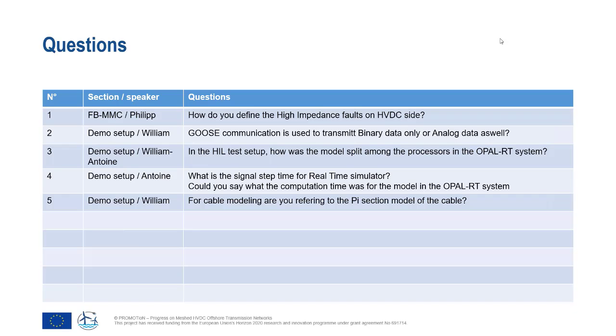It's just an exemplary value to analyze the stress of a high impedance fault on the protection strategy itself. In a cable-based system, especially for offshore cable-based systems, all cables are grounded and the return path is usually quite good, so we are more in the below-ohm range for faults.